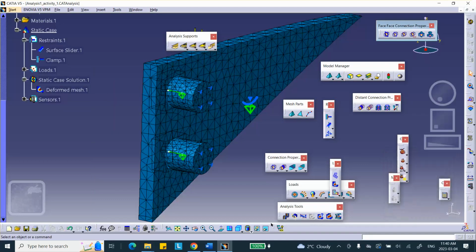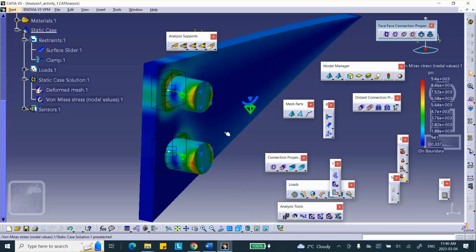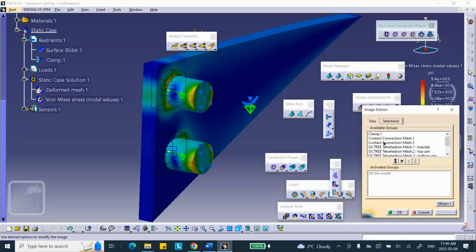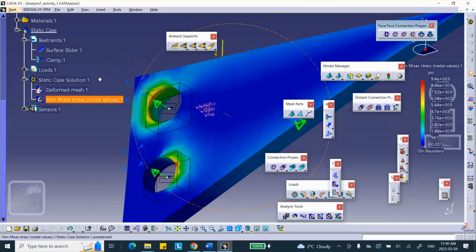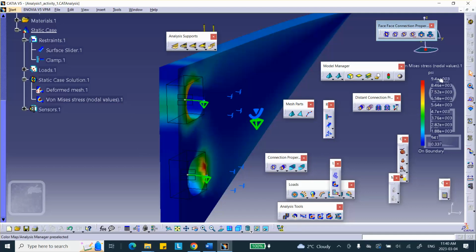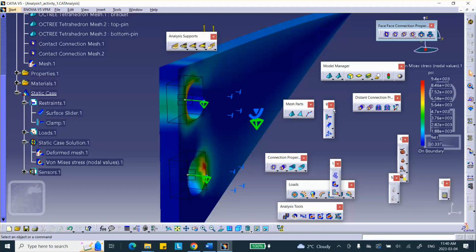If you want to look at the von Mises stress, for example, it's so easy to generate good-looking garbage, but anyway, if you want, it's right here. Now, if your main concern is the bracket itself, not the pins, you double click on this contour, on the selection, and say just show me the bracket. Notice that now it puts the pins away and shows you the bracket. Okay, stress distribution in the bracket. As I said, although you can look at these numbers, be very careful not to take them literally as good, because we don't know the effect of the mesh. So pretty much that's it.